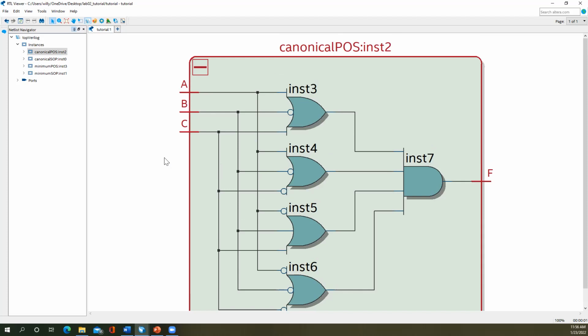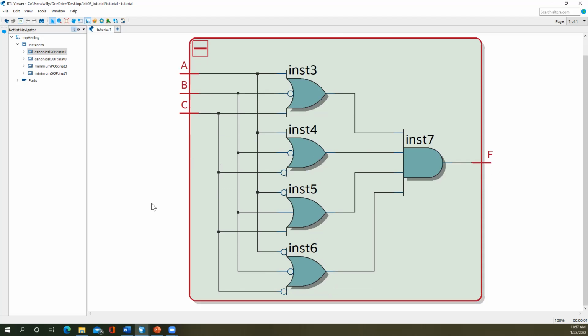Go ahead and label my wiring connections and all, then write my Verilog based on top of that, my hardware description, and then use this RTL viewer after I got done writing it, then to double check that my circuitry looked like what I expected. Even when the simulation ran, I like to take a look at this.